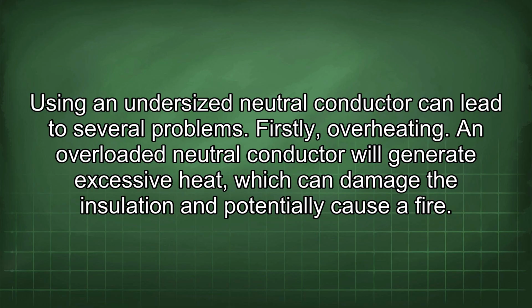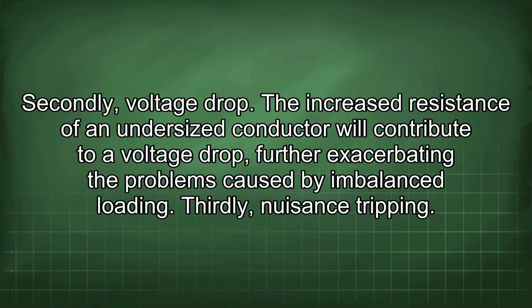Firstly, overheating. An overloaded neutral conductor will generate excessive heat, which can damage the insulation and potentially cause a fire. Secondly, voltage drop. The increased resistance of an undersized conductor will contribute to a voltage drop, further exacerbating the problems caused by imbalanced loading. Thirdly, nuisance tripping.